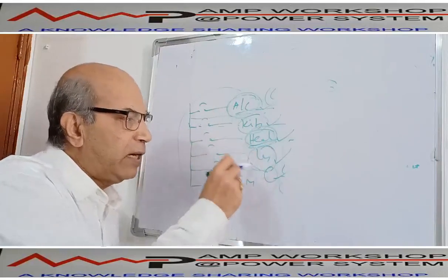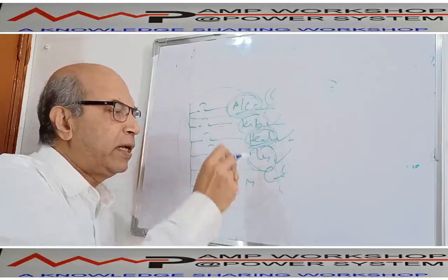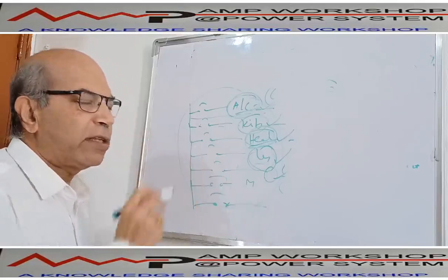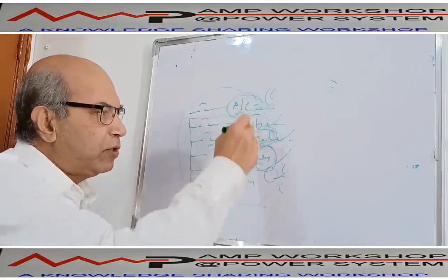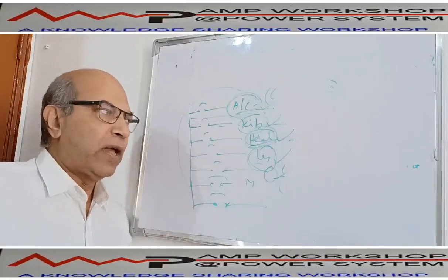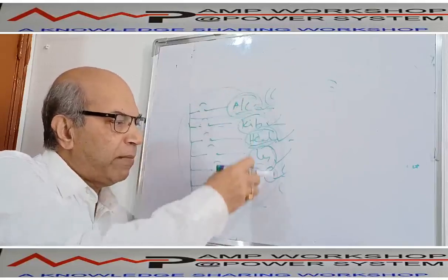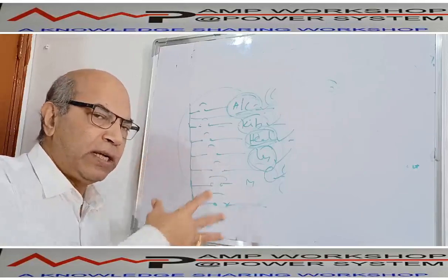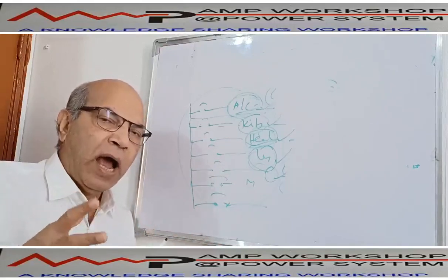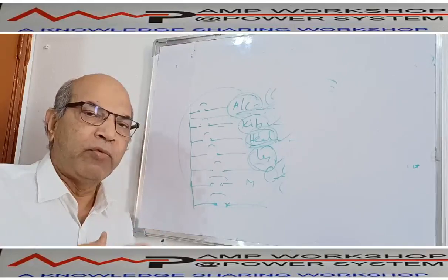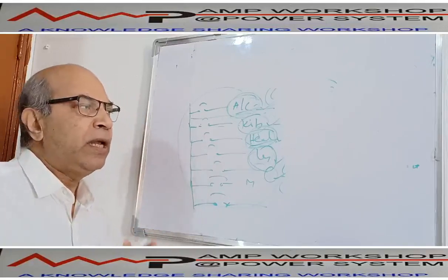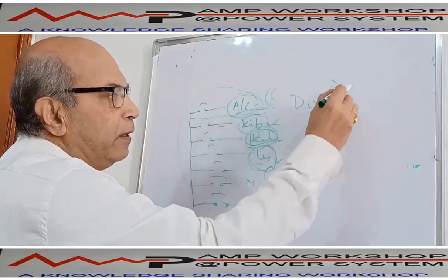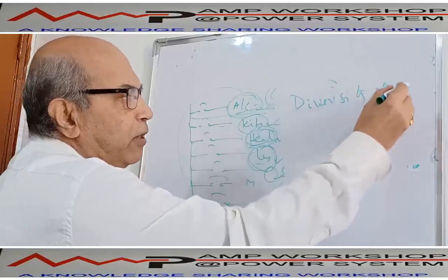Suppose at night time when AC is running, the lighting load will be running. Then there is a ventilation load, meaning all the fans are running. So among these there is again a diversity. Although all of these have a maximum demand, all the maximum demands will not come simultaneously. To decide how much total maximum demand can come at a particular instant of a day, we use a diversity factor.